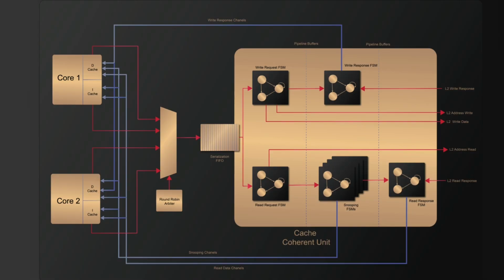To support multi-core communication, we develop a cache-coherent interconnect that links all cores to a shared lower-level cache. It follows a snooping-based protocol and implements the MOESI cache coherence protocol using the industry-standard AXI ACE interface. This ensures consistency across cores during shared memory operations.